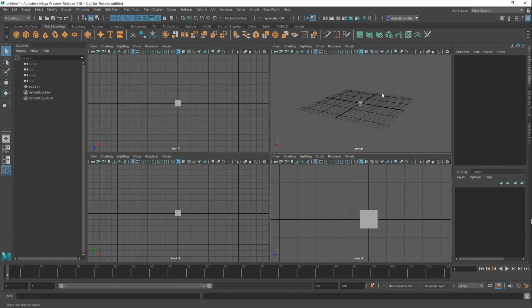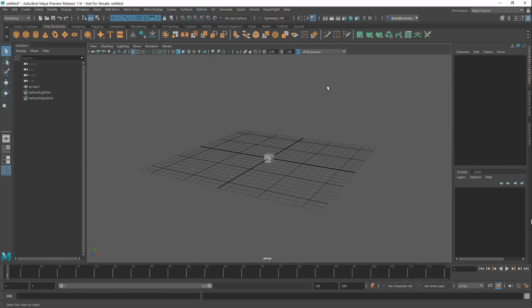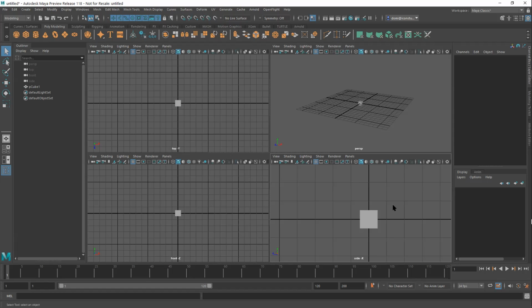Before I zoom in on all of these, here's another quick way to get to these different windows. It's not really a hotkey, but sometimes, as you get more sophisticated and use Maya more, you don't always use the icons. So you might want to try using what they call hotkeys. The first one I want to show you is the space bar. Whatever window your mouse is hovering over, the space bar will go to it. So in the side window on our lower right, I hit the space bar to get to that. You're going to get used to moving around a lot in Maya, because it's 3D, so it really is helpful to look around.